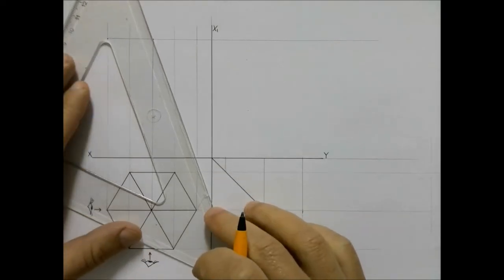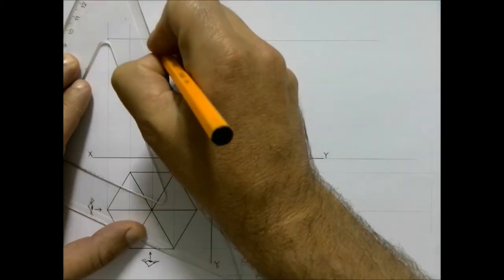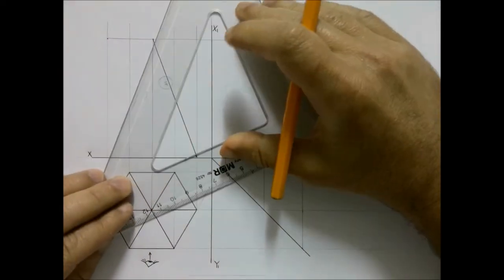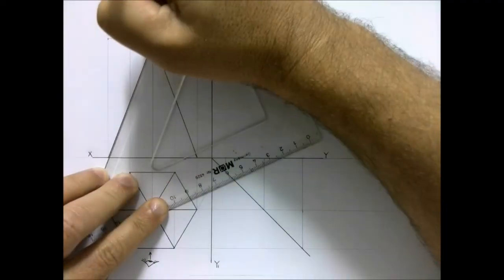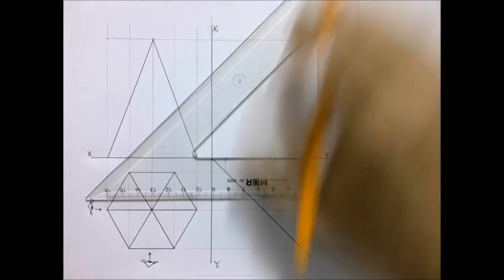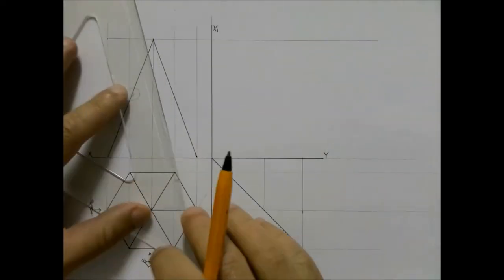My front view will have the perimeter lines, a profile if you may. Looking like so. And then obviously when looking from this eye point of view, I'm going to see this surface over here, this surface over here, and this surface over here. Anything behind this line basically will be in hidden detail or will not be seen.